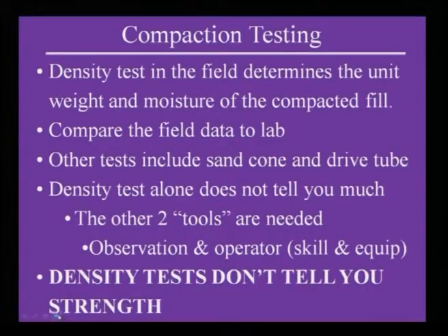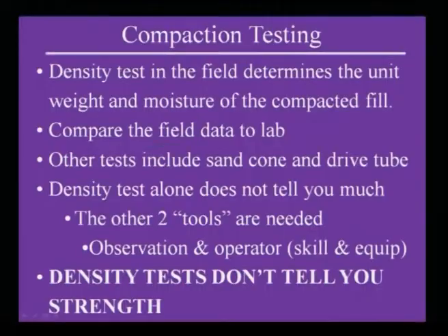Once you do the field density test by means of the nuclear test, compare the field density data with your lab. Other tests include sand cone and drive tube. Density test alone does not tell you much about this observational operators. Density tests do not tell you the strength. Remember, whatever density test you are doing, that only gives relative density and moisture content. It does not give the strength of the soil achieved.